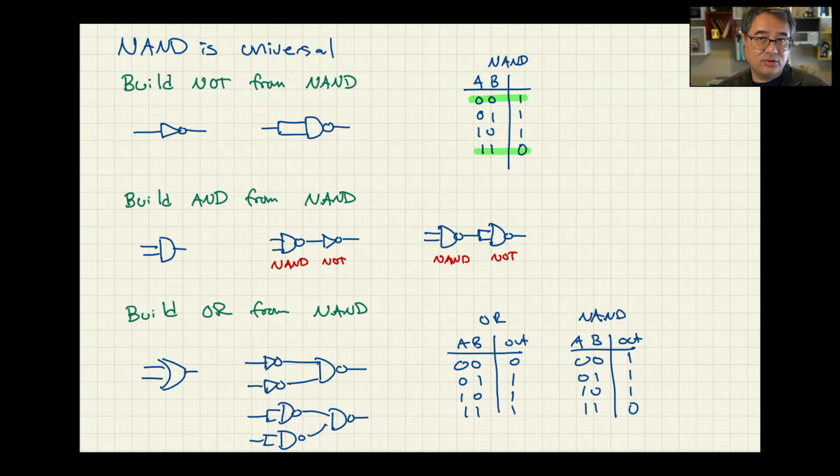They're called things like programmable logic arrays or field programmable gate arrays. Basically, they're just a whole bunch of NANDs, millions of them, all sitting in a grid. And then you can use a special programmer circuit that internally hooks up those NANDs in the way that you want, and you can implement any logic circuit that you desire. Usually these chips have about 50 or 60 inputs coming into them, and then you can use those 50 or 60 inputs to construct any kind of logic circuit you want.